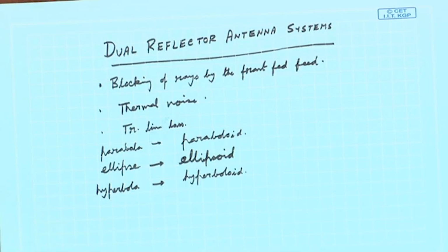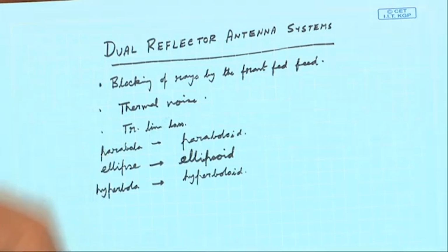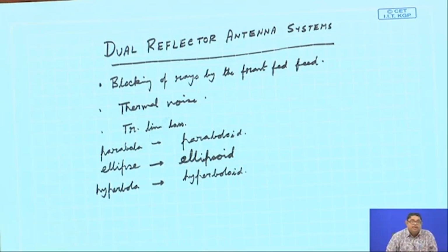Also, the feed, receiver and transmitter can be placed behind the primary reflector. Also, a modest amount of reshaping of the subreflector and the main reflector can be carried out in order to give a more uniform aperture field distribution, hence higher efficiency is obtained. By reshaping the subreflector alone, the desired effect may be obtained. Such reflectors are known as shaped reflectors.